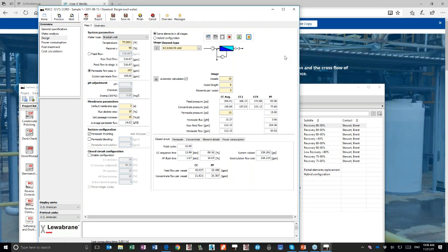With silica, I can tell you 300 ppm is kind of the guideline with antiscalant and neutral pH, and we've pushed that over 500 and run consistently without seeing an increase in pressure. So the max concentration factor, max TDS, is a function of pressure. Whatever we can do, if we're not limited by scale, we can go up to the 600 psi. I think that answered it. Oh wow, yeah, I think that answered it.